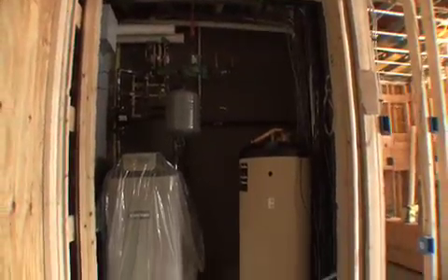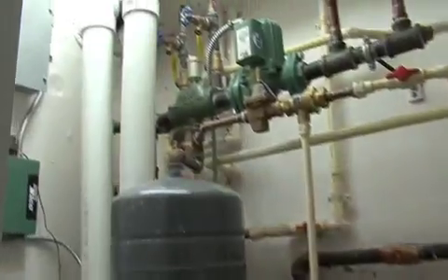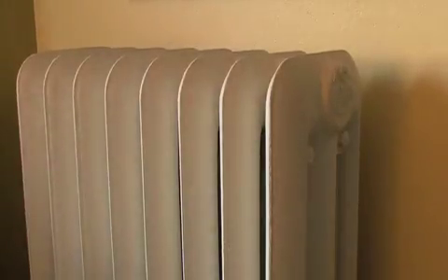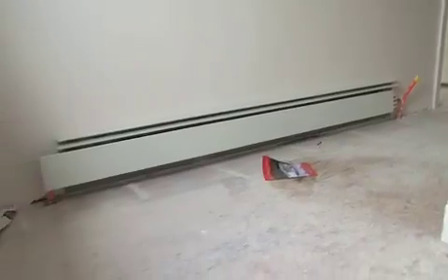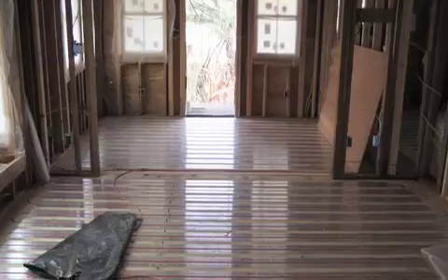Other forms of radiation play an important role in the transfer of energy into or out of a home. I'm sure most of us have been in those older buildings where you've got those old cast iron steam radiators, and those get really hot. You do feel much more of the effects of radiation, and you walk into a room and you feel that heat source. Today's baseboards don't operate at quite the same high temperature, and there's the other convection heat transfer mechanism that is working with those.